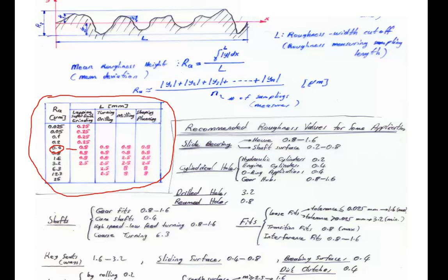In that case, since the measured roughness size is in this order, change the sampling length, not 0.8 but say 2.5 as the cutoff value. Using this number, perform the experiment. If the measured value is equal to or close enough to the roughness size assumed or guessed at the beginning, then yes, do not repeat the experiment. Till you find the guessed value equal to the measured value, repeat the experiment.